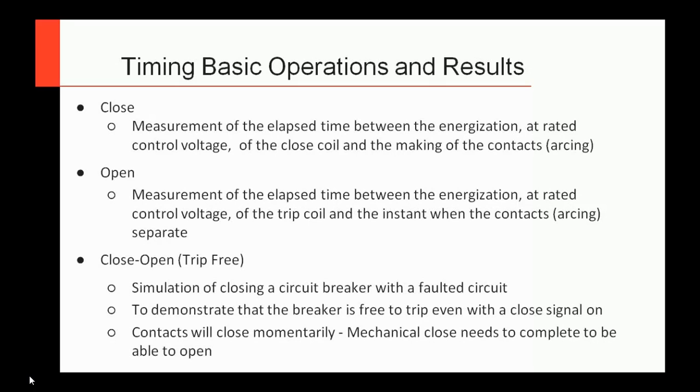Something else you'll see is the close-open, referred to occasionally as trip free. You'll hear dwell time. It's a real world condition where the breaker closes in, sees a fault, and trips back out immediately to clear it. What we measure here is, when you close the breaker and that first metal-on-metal contact touches, that's your time 0. Then you keep recording, and the breaker might not even come all the way closed. It'll come back open, and as soon as the contacts separate again, that's your other time you measure, and the difference between them is your close-open time, or your dwell time. These are the most common measurements performed.